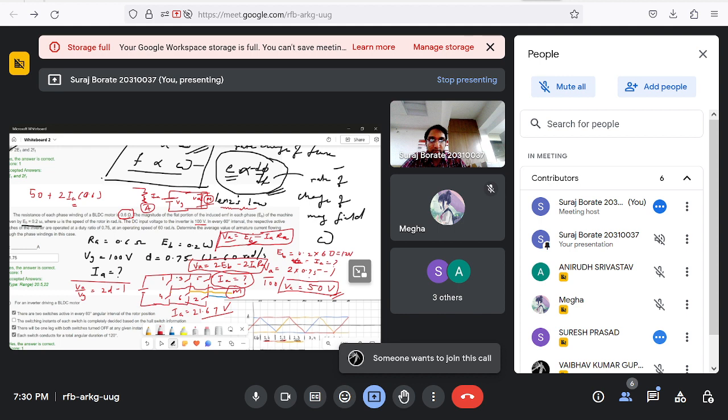But if you have some switching over here, you will get similar switching over here and similar switching over here. You cannot have a different frequency here and a different frequency there. That won't happen, because it is the same I coming over here. The same frequency will be carried over to the torque. So if the omega increases, the frequency increases.